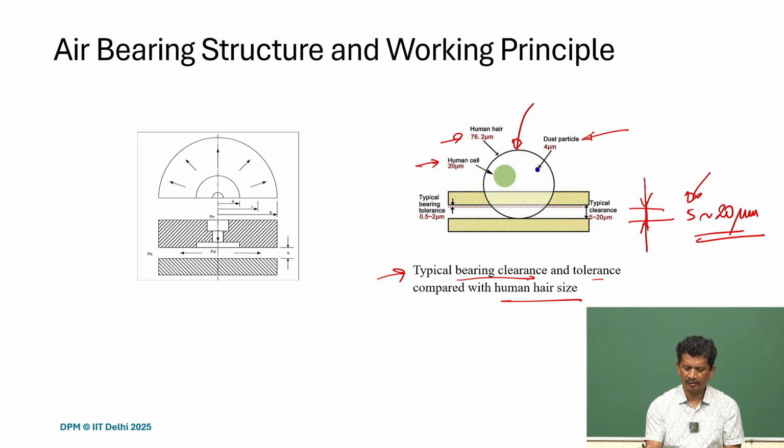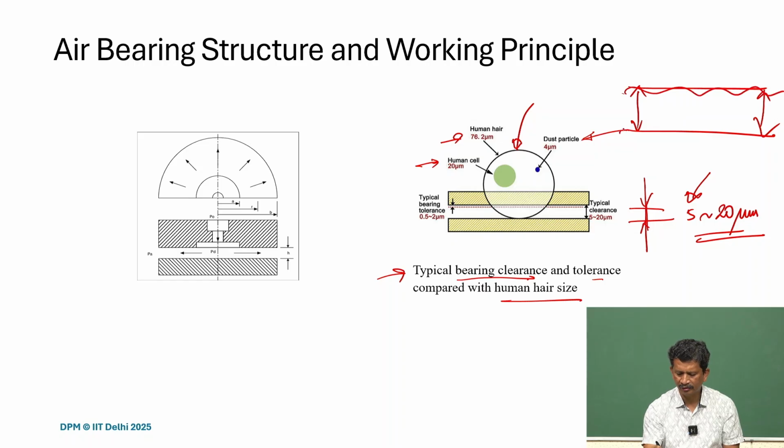If this is my gap, then the flatness requirement should be at least 1/10, so the surface flatness may be below 1 micron. We should be aware of that.